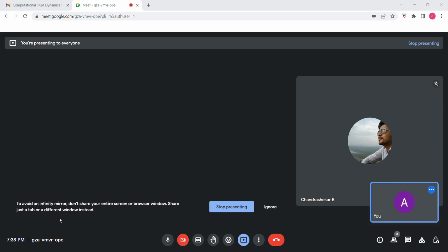So there should always be an optimum compromise between desired accuracy and solution cost. We should not always go for finer meshes because we can't do large computations, and similarly a larger grid size would give faster computing, but the results would not be accurate enough. So the answer to this question is to generate an optimum grid, which is a compromise between desired accuracy and the solution cost.